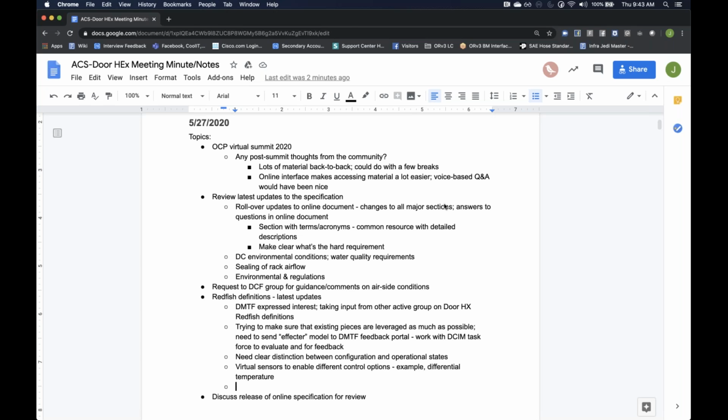Mike, I guess a couple of areas that we may have previously brought to Jeff's attention: for example, we just talked about differential pressure, but differential pressure can have different units depending on the medium that you are measuring. For example, for airside differential pressure, pascals is more than enough.